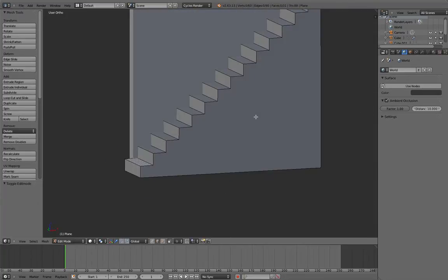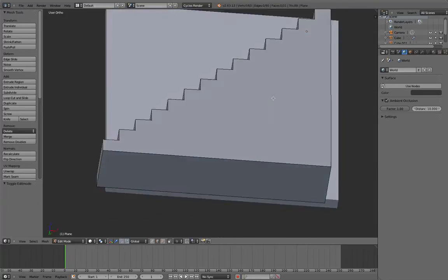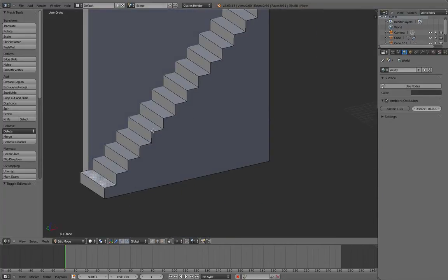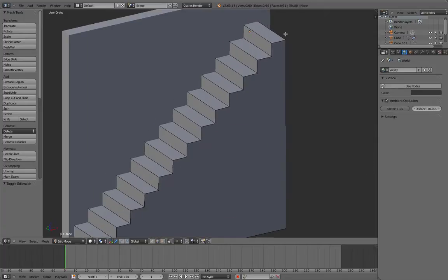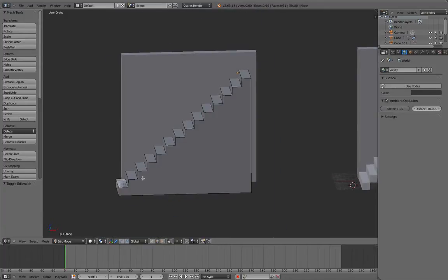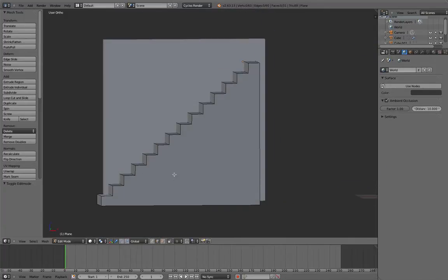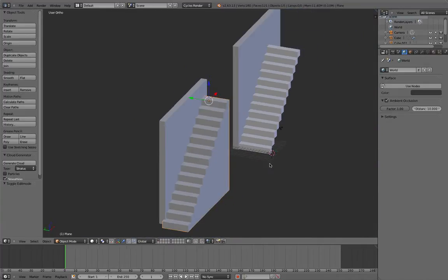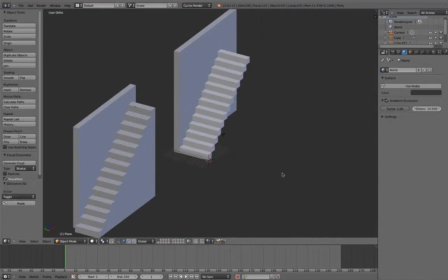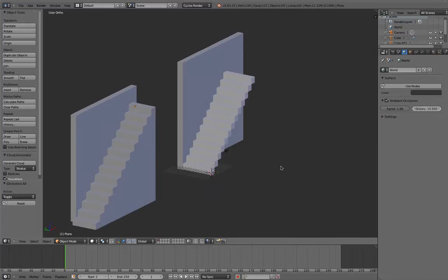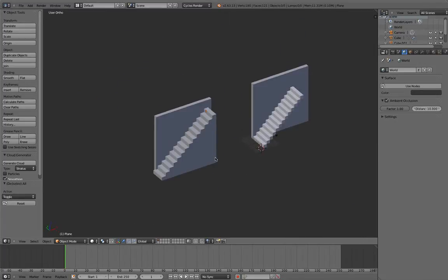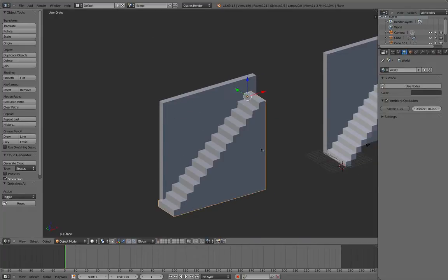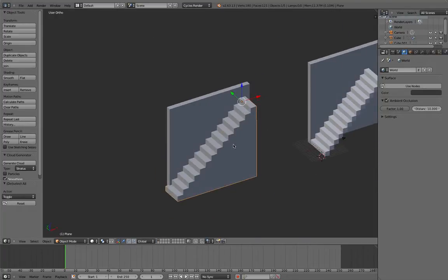This is what I would call good use of n-gons, when you have quite a complex thing there, but you just want it filled in with a flat surface. And that gives us a similar but different result. And this is the method I prefer for most stuff.